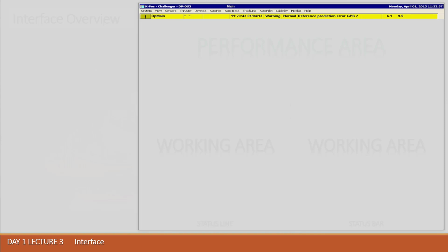In the performance area, the first icon you see is known as status. In that icon you see information about the position reference equipment selected and about the weight calculated for each PRS, and in case a thruster, sensor or gyro has any problem or failure, here you will have an indicating circle with the name of the failed equipment group.